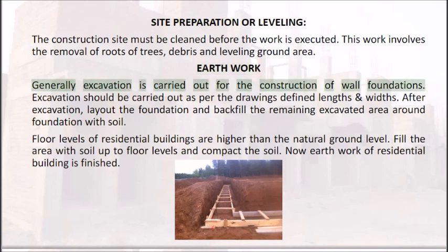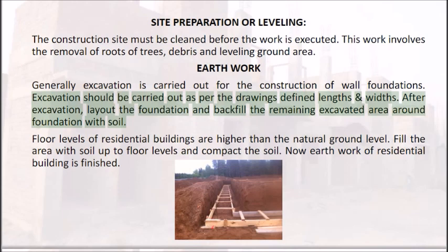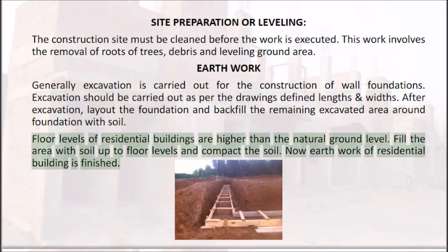Generally, excavation is carried out for the construction of wall foundations. Excavation should be carried out as per the drawing-defined lengths and widths. After excavation, lay out the foundation and backfill the remaining excavated area around the foundation with soil. Floor levels of residential buildings are higher than the natural ground level. Fill the area with soil up to floor levels and compact the soil. Now earthwork of the residential building is finished.